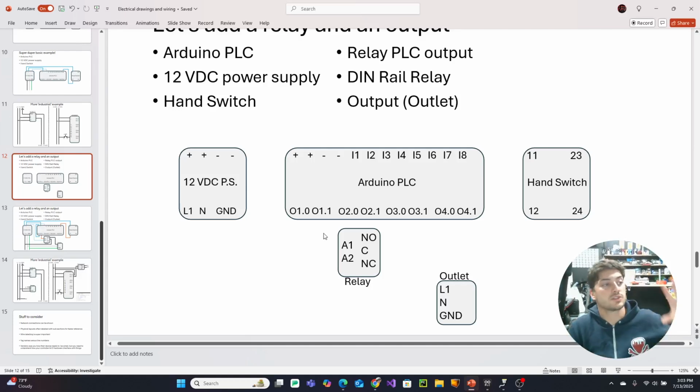So you use low voltage DC power to change the state of a relay, and then a separate electrical connection is made on the other side of the relay. So I think we'll probably get more into relays as we continue doing the tutorials in this series, but it's arguably the most important component in the world of industrial automation and controls.